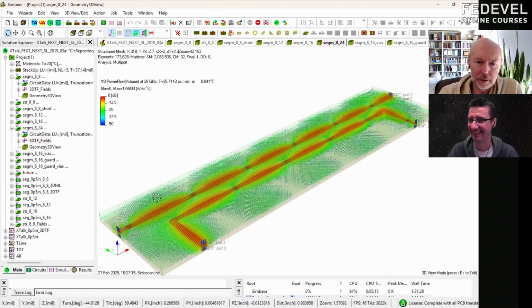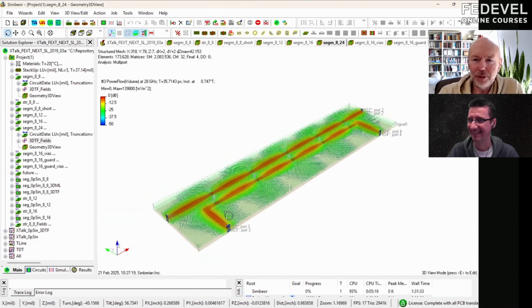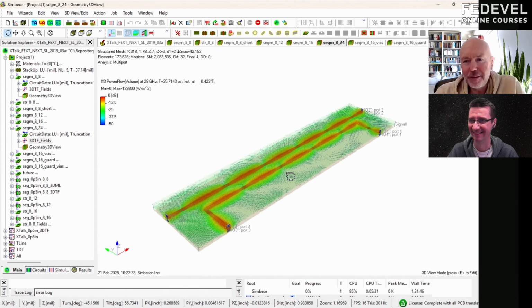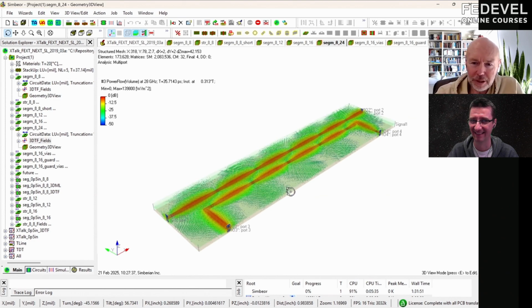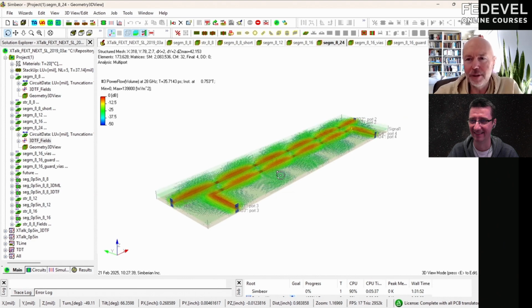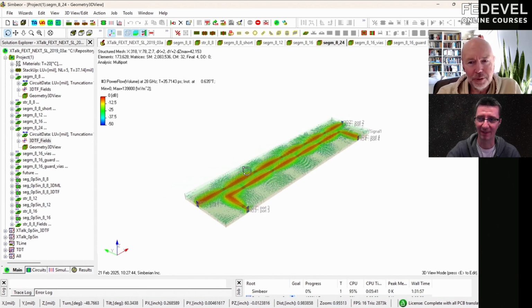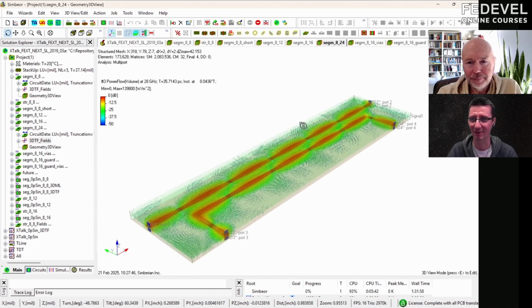So this one gets crosstalk here, but right here, far-end crosstalk in this case will not matter because the receiver is here. And from this signal, you're not getting far-end crosstalk on this end. So getting signals like this, it's safe in here from the point of view of far-end crosstalk. But you still have energy going sideways everywhere. And if you put them in the same direction, it's going to be worse or what?